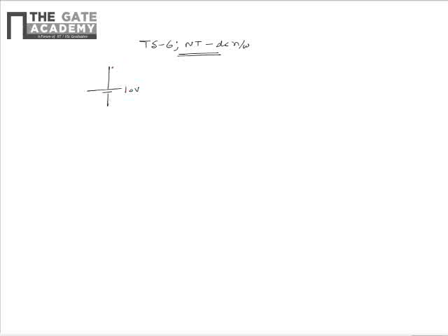It contains a 10 volts voltage source connected in series with a 10 ohm resistor. This combination is connected in parallel with a 1 ohm resistor. The drop across the 1 ohm resistor is measured as V1. There is a current source which is dependent on this potential V1 connected in parallel with the 1 ohm resistor. The current of the dependent current source is V1.